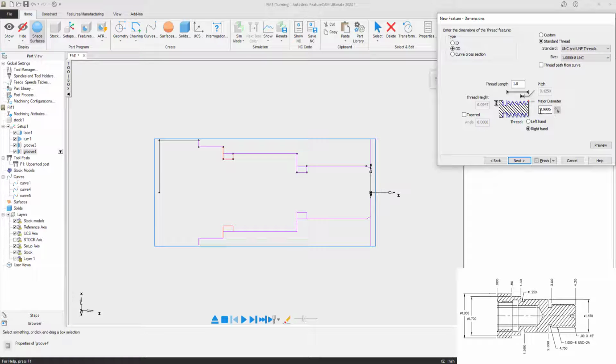And if you'll notice, look at that major diameter. That is being pulled from the Machinery's Handbook to the nominal dimensions. So we already made it to that, so we're in good shape, because our turning tool is what establishes that diameter, not the threading tool. So I'm going to put my thread length, like it says on my print here, at 1.3. And I'm going to hit preview.